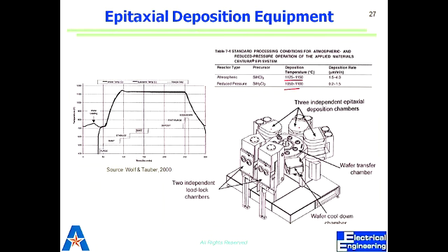In this case, we are loading a wafer and purging the gas, and then we are ramping the temperature, and once it gets there, we stabilize it, and then probably the gases start flowing in. And still, it takes a while before we start counting the actual measurement. Once the deposition happens, then again we have to purge. So the whole process needs to be well controlled in temperature, flow of gases, the diffusion of gases and reaction, how fast it moves. Right.